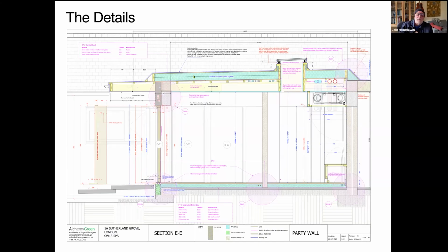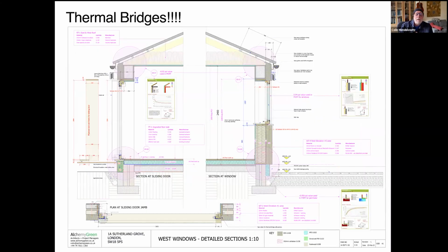These two layers of insulation were put in place by glue, so we have no fixings through here. This whole sandwich over here is a glued sandwich with a top layer on OSB of standard felt roofing. So quite simple. The MVHR section tucks under the existing structure, and this forms the sort of spine of the services.